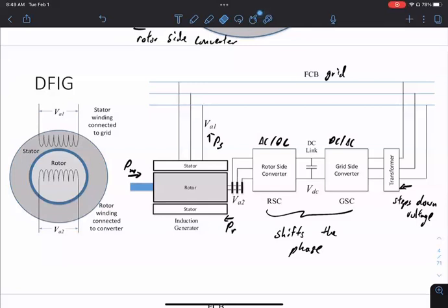So if you look at this, you will think most power will flow through here, but that's actually not the case. For this to provide reactive power, about 1/3 of active power has to go through here. It's because there's a lot of reactive power element here, so you need a not insignificant current to go through this side. You need some current to go through here.